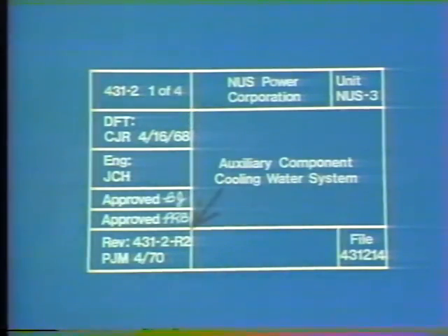This block indicates any revisions that have been made to the print. Over the years, as manufacturers change and improve their products, they'll issue revised prints to reflect the changes. Different types of prints will have different information in the title block. For example, a detail print of a machine part might contain the material the part is made of and the tolerances that can be allowed if the part is to be refabricated.